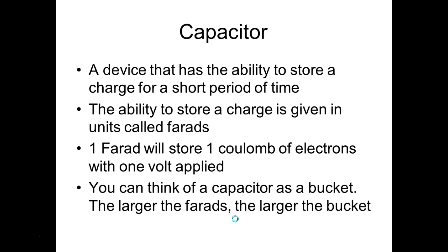So the capacitor charges and discharges at what we call an exponential rate. Y'all know about logs, right? Logarithms. You okay with that? Well, we have two types of logs: a natural log and a common log. A natural log is what we use to work with things that vary in curves, an exponential curve.